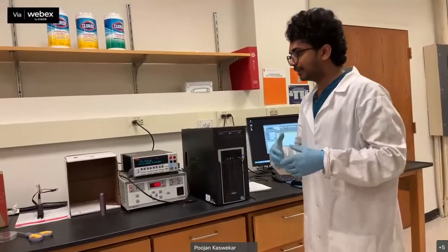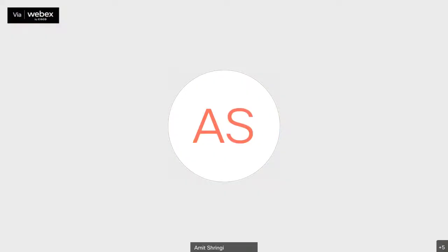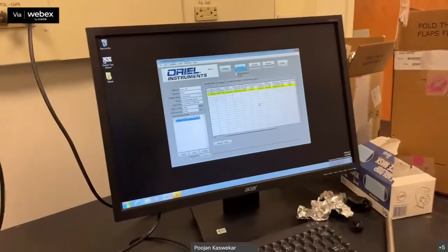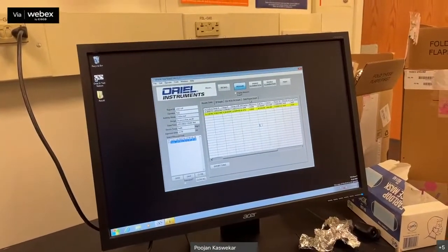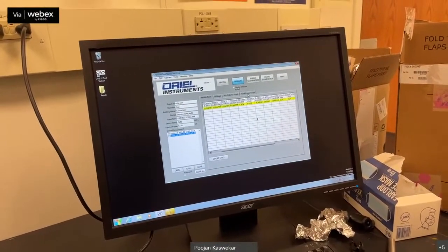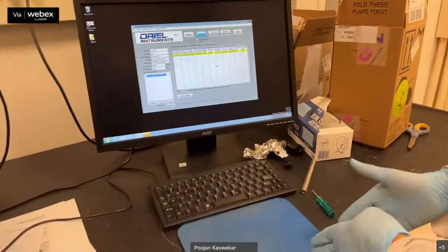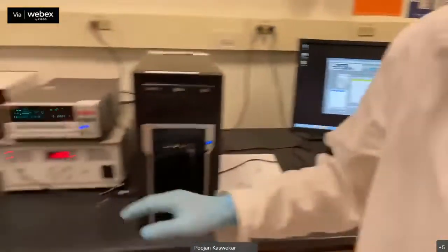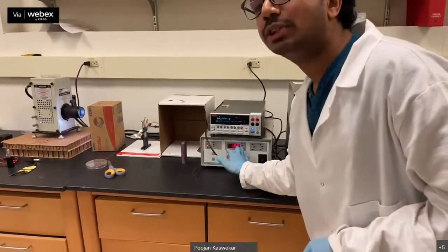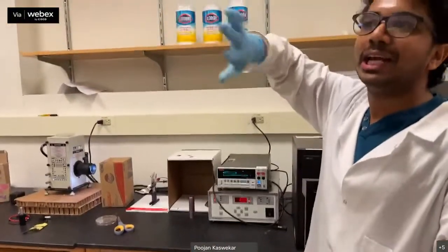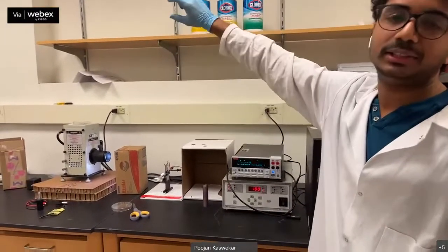Okay, we have one more question from Muhammad Umar Rahman. He is asking, is direct reading of MPPT, maximum power point tracking, possible? Yes, maximum power point tracking is possible, but you need to change some of the settings here. Typically you calculate the maximum power point for the solar cell with different illumination intensities. So you change your wattage here from 10 watts to 100 watts, and track the MPPT of that solar cell through the whole device.